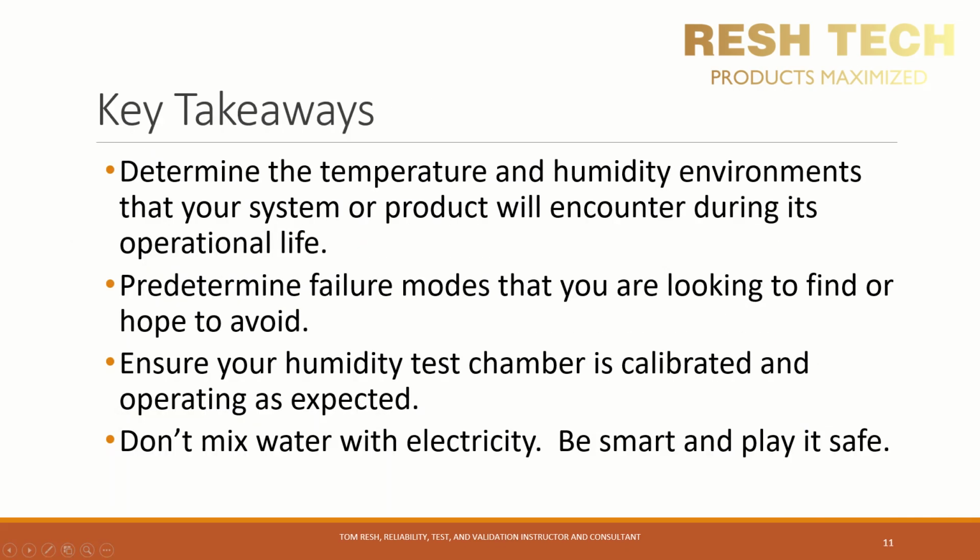Some of the key takeaways from this humidity testing video are: determine the temperature and humidity environments that your system or product will encounter during its operational life. Predetermine failure modes that you are looking for or want to find or hope to avoid. Ensure your humidity test chamber is calibrated and operating as expected, and also verify your sensors are working and maintained. Don't mix water with electricity. Be smart and play it safe.